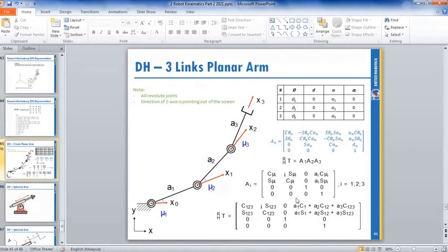After you multiply, you get this matrix. This is your position, orientation matrix because it contains your x, y, and z, cos and sine. This is your position matrix, referring to your base robot 0, 0, 0 coordinate. Your base robot, we call world frame, world reference frame. So you know the position of your gripper, referring to your world reference frame here.